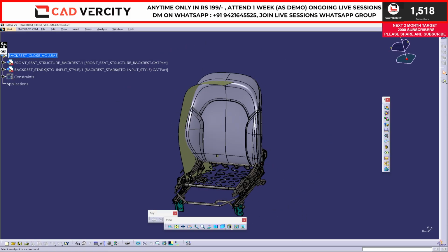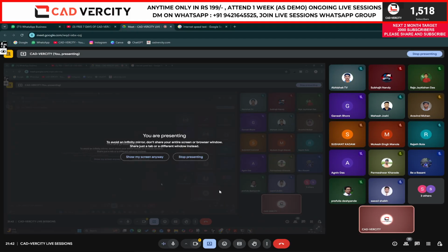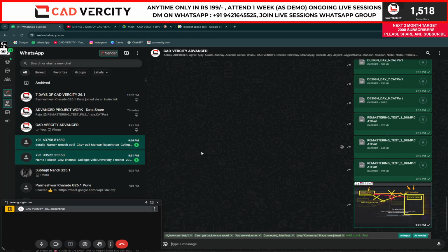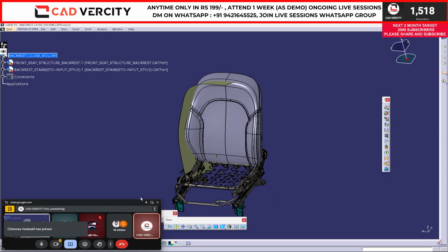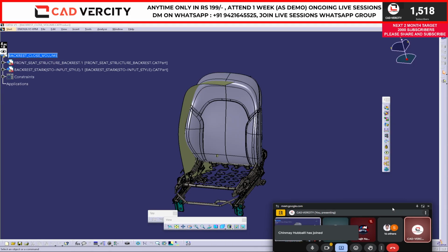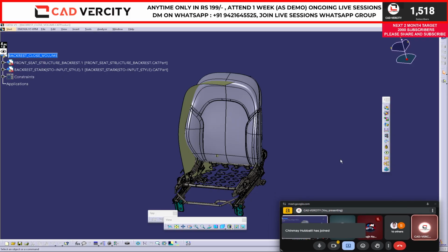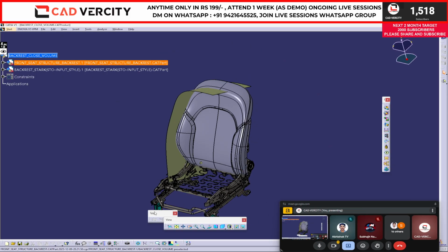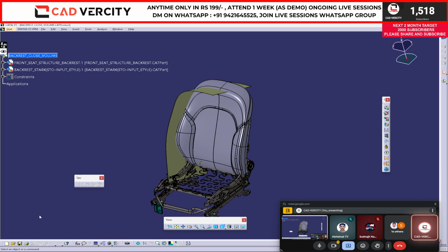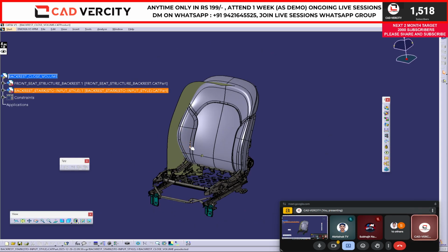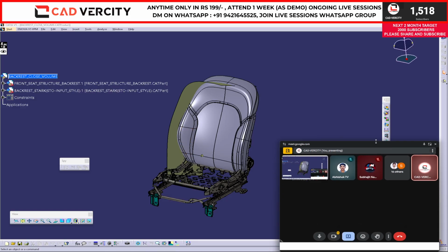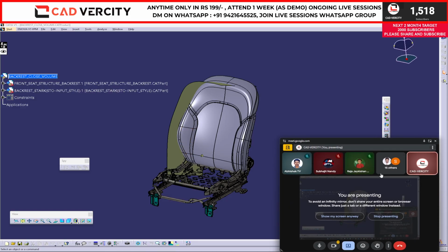No, no, no. It is a bad practice. Never draw any sketch on any face or any plane. Okay, Abhishek? Never. We will only use our axis system. This is our master rule. Never use any plane or face. Previously, I was using like that. No, it is wrong practice. Don't follow that one. Okay. For beginners, let me mention this point.